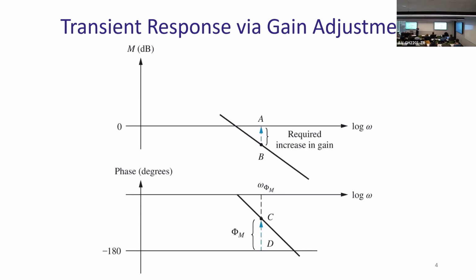Okay, this was the idea of designing controller K. So you're changing gain until this plot cuts exactly at that point where you have desired phase margin, right? And then you just pull up to that point and will close. Because adding gain, all it does is just shifts up and down the gain plot. Right? That's it. This was the original idea.